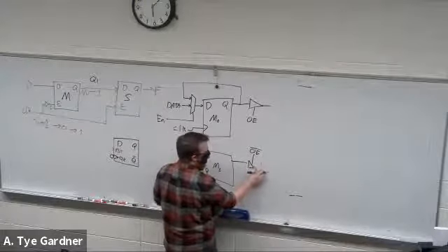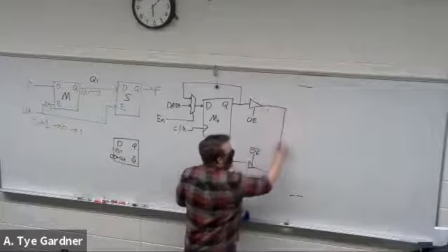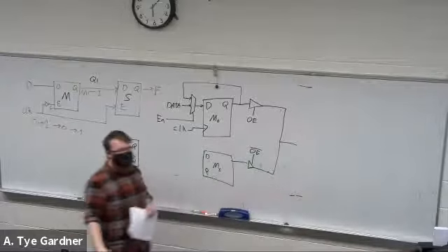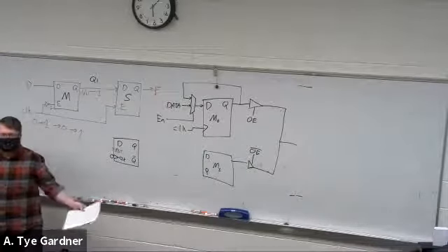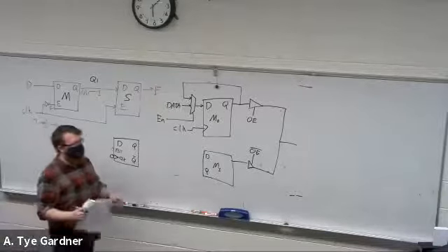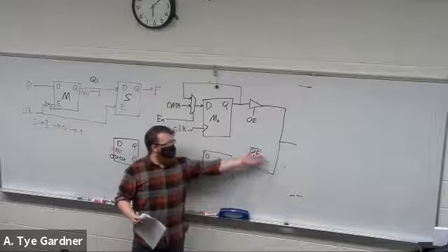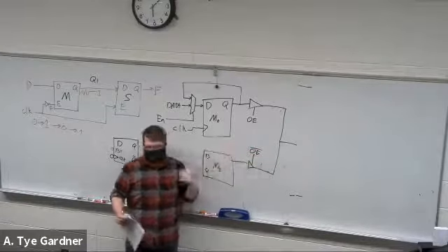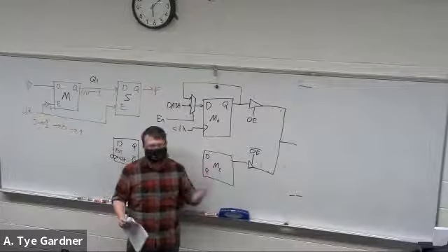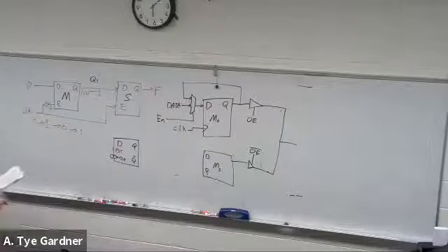Oh, not an inverter, sorry, just a buffer. These can actually both attach directly to the same wire without the need for a mux. So it's a little bit simpler, because buffers are simpler than a mux. And they can both share an output wire because only one of them will be driving it at a time. So that's one purpose of output enables.